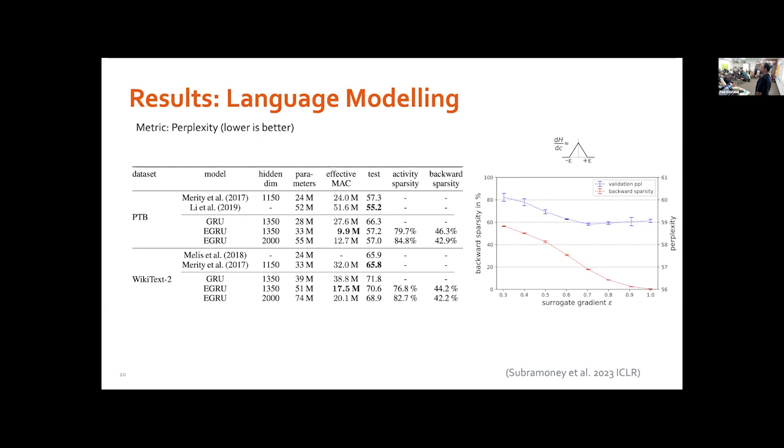I get that you have to perform fewer MACs, but now you need to keep track of what events you had when, and you need to store all of this. You're basically translating from a dense matrix where you access every element, with a lot of MACs, to a sparse matrix with more complicated indexing, and then for the few values where you do need to index, you have float operations. But I'm never sure, when people make these comparisons about sparse and dense, that it's really so much cheaper. Why would it be worse than normal?